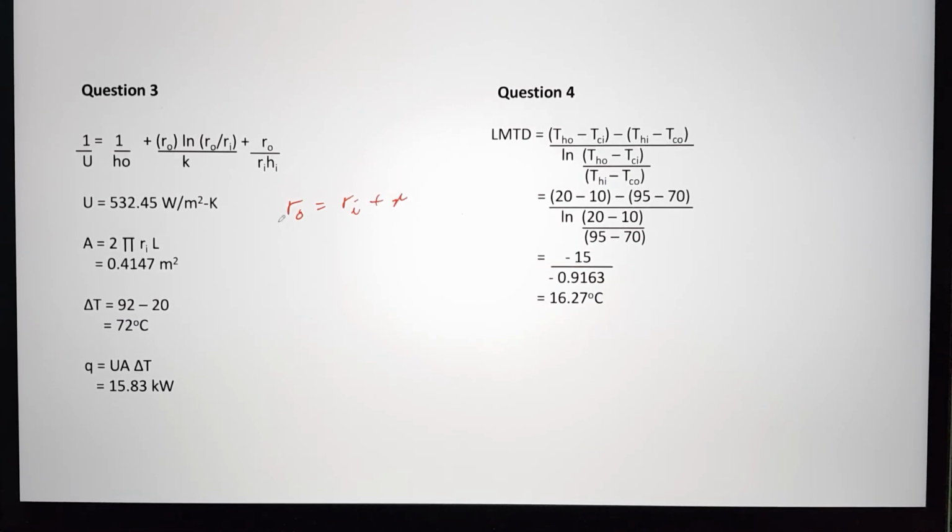It is being heated by hot water which flows on the outside of the pipe. So it is very clear cut, whereby mango juice is flowing on the inside of the diameter, whereas on the outside hot water is flowing. The film heat transfer coefficients have been given to you, the thermal conductivity has been given to you, so the same steps apply: you need to calculate the overall heat transfer coefficient followed by the calculation of the rate of heat transfer.